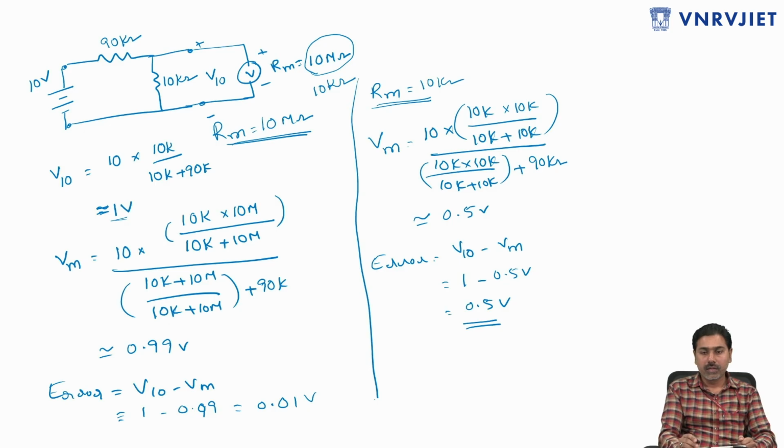The loading effect is when we use a low resistance or improper or extra load on the actual circuit or measuring unit, that device load is also adding and producing some error. That is due to the loading effect. We get some instrumental error. And how to minimize this? By selecting the proper measuring device with suitable internal resistance for minimizing the error.